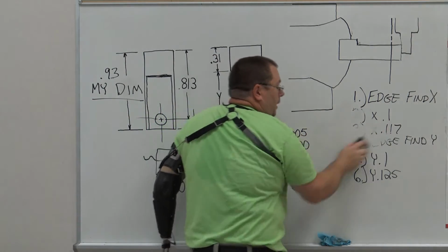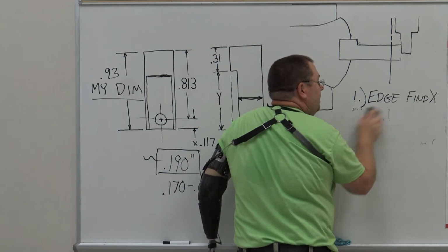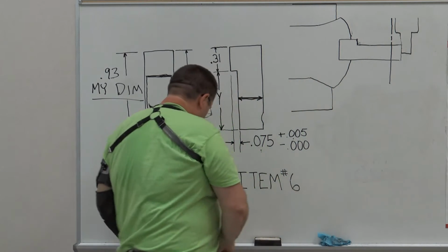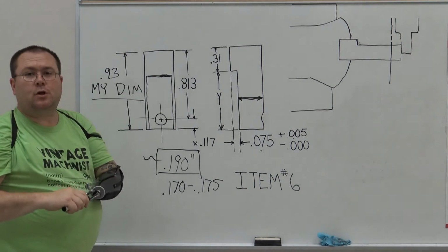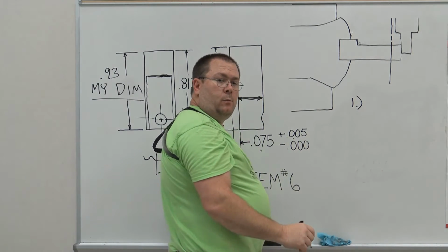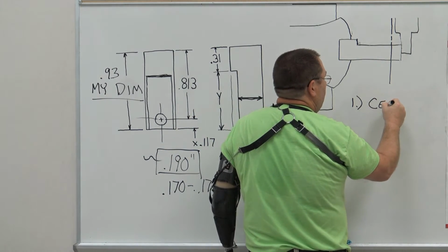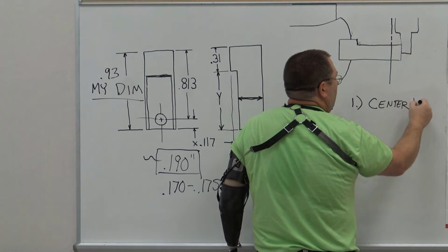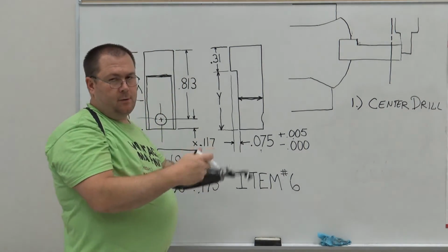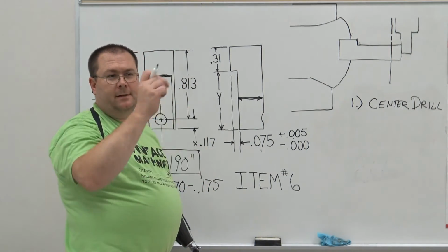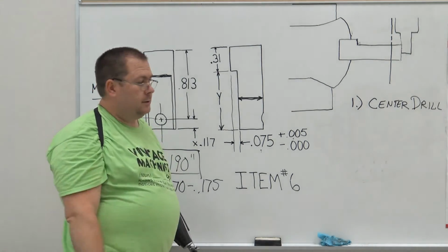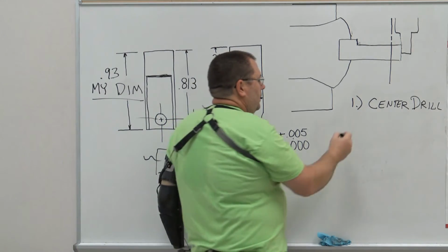So now we're going to follow the same drilling and reaming operations that we followed a couple of times previously. Right? Now we're ready to put the hole in. So step number 1, we want a center drill. Remember, max RPM, if I did my math, it still works out to be a really big number. Come down and touch it. If you touch it within 20 or 30 thousandths, I'm good. Cutting oil, this is tool steel, remember.